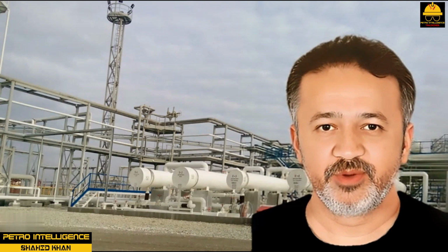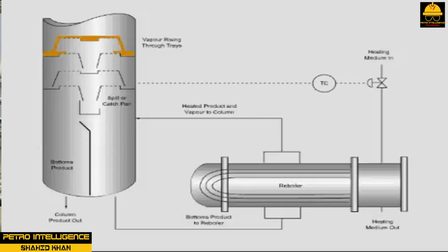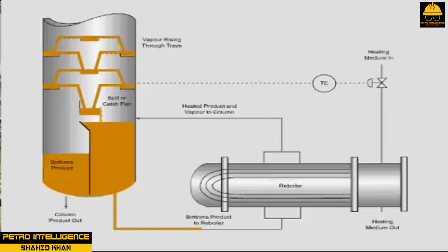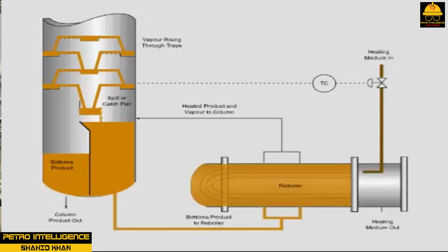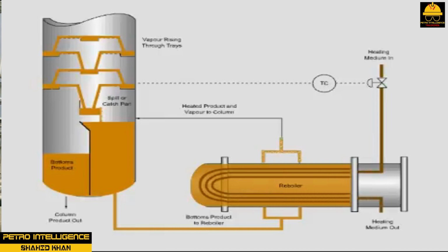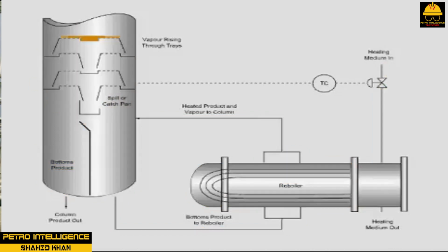Vertical and horizontal thermosiphon reboilers. A thermosiphon reboiler is a fixed-head, single-pass heat exchanger connected to the side of a distillation column. Thermosiphon heat exchangers can be mounted vertically or horizontally. The critical design factor is providing sufficient liquid head in the column to support vapor or liquid flowback to the column. Natural circulation occurs because of the differences in density between the hotter liquid in the reboiler and the liquid in the distillation tower. One side of the exchanger is used for heating, usually with steam or hot oil. The other side takes suction off the column.